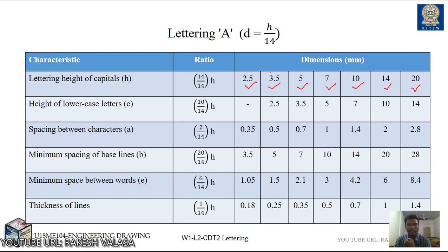These are the standard heights in engineering drawing. I am taking this 14 as the lettering height of capital letters. For calculating the height of lowercase letters, the ratio is 10 by 14 h. Here h is 14. 14, 14 get cancelled. The height of lowercase letters is 10.